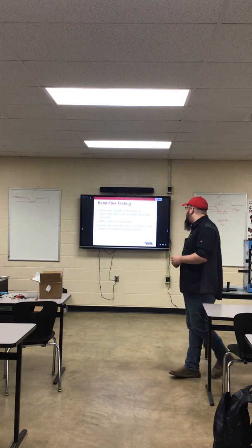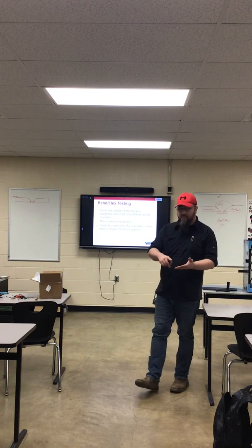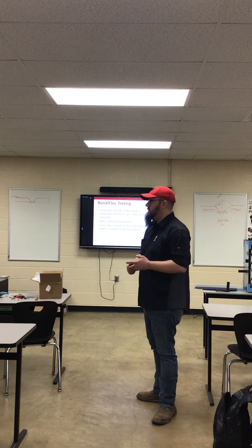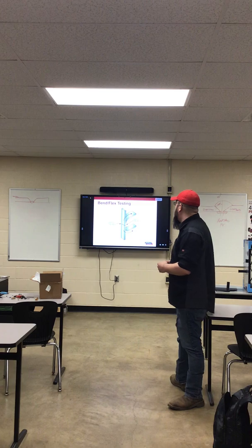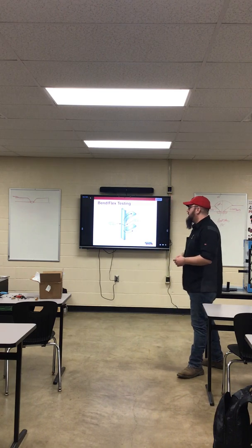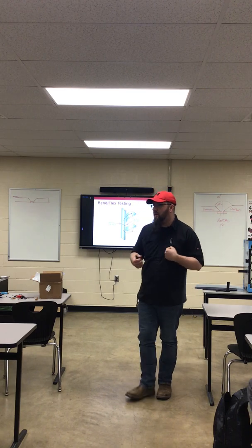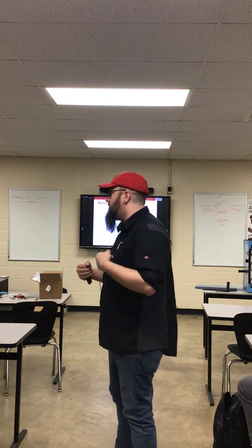Generally named for the orientation of the weld in respect to the bending action. Okay, so we have side bend, we have face bend, we have root bend. So this should look pretty familiar, right? The root of the weld. What kind of force is being exerted on the root of that weld? Is that going to be tension or compression?